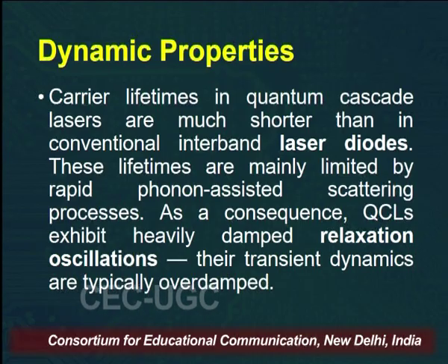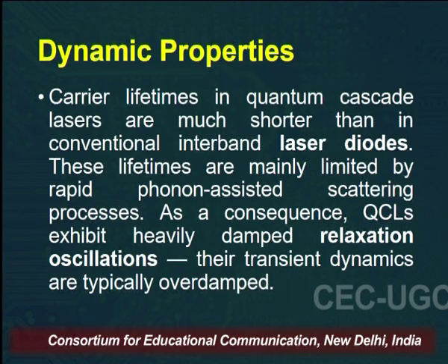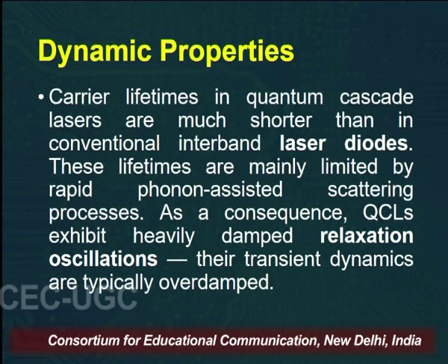These lifetimes are mainly limited by rapid phonon assisted scattering processes. As a consequence, QCLs exhibit heavily damped relaxation oscillations.